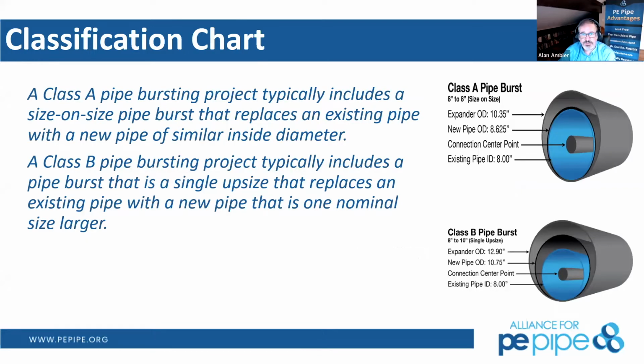Here's another way to be able to look at this. And one of the things that I would like for us to realize as we increase the OD of that pipe, the majority of that increase now comes through what's called the spring line of the pipe. It's the theoretical center. Now that theoretical center with a larger OD now raises as well.